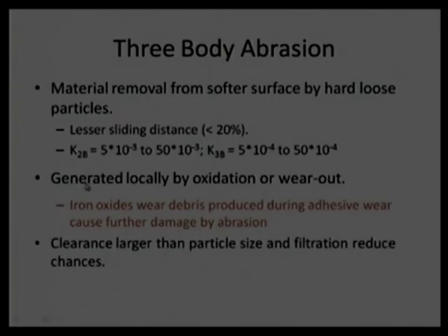These particles, the third body, generally occur because of oxidation and detachment of the oxide layer from the surface, or some other wear phenomena. Maybe because of adhesion, junction formation occurs, and then a fragment of the surface or the adhesive junction may be generated as wear debris, that will cause abrasion.